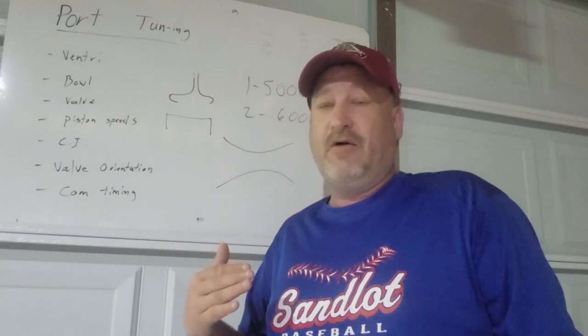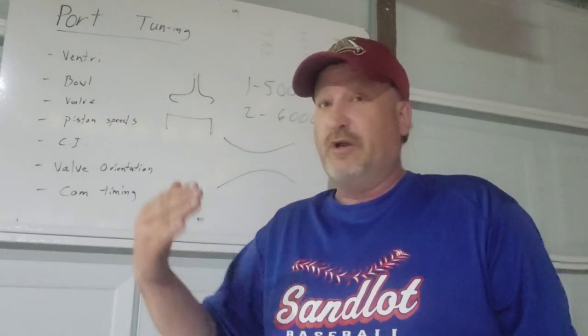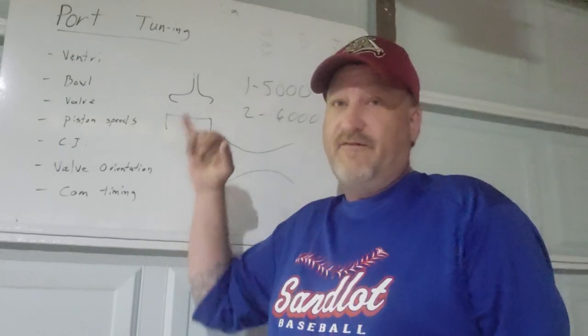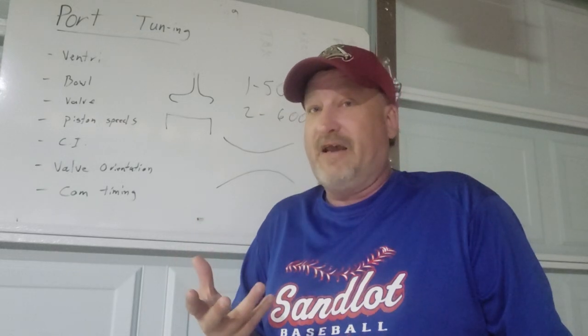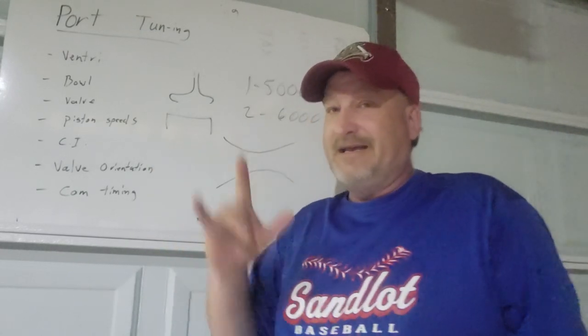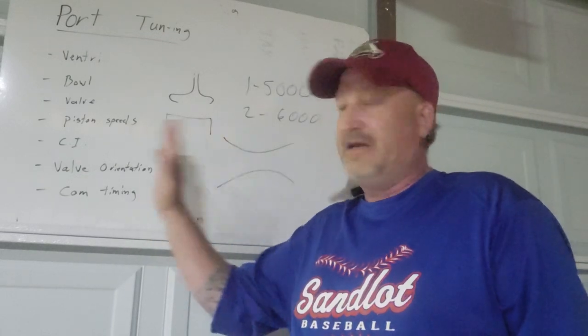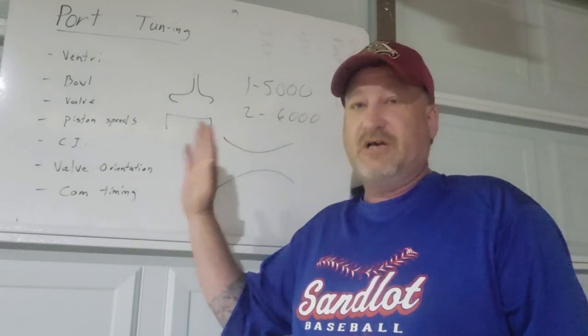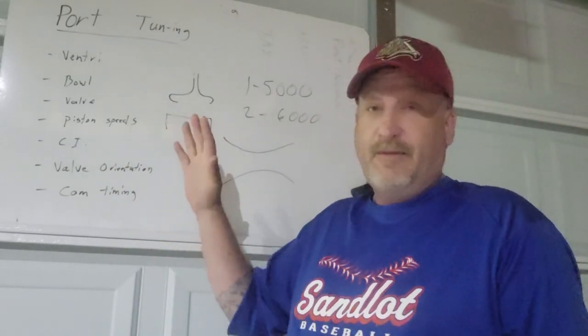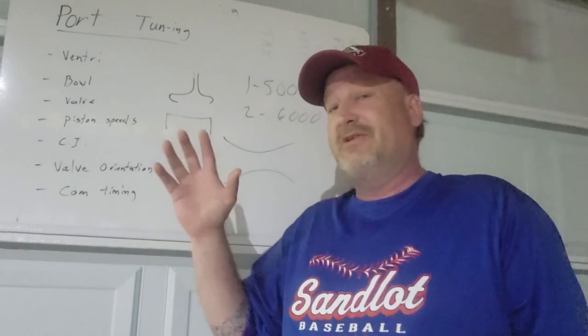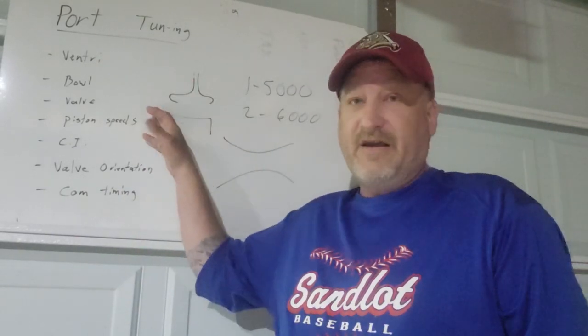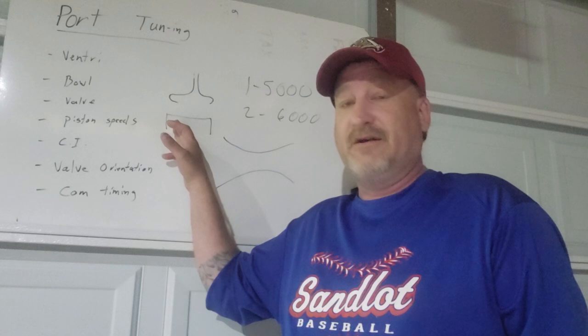As the piston travels down, the creation of vacuum is going to increase. Initially, when the valve opens, it's not creating any vacuum until you get into the exhaust system. We're not going to get into that quite yet, because the exhaust system has a lot to play, again, within port tuning. Not only the exhaust port, but what kind of pressures are left behind in the cylinder.